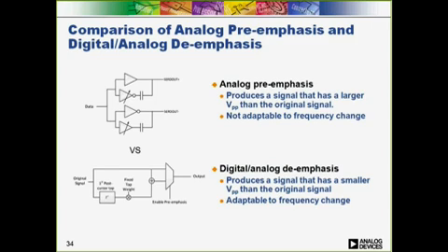This slide summarizes the differences between the emphasis methods that ADI uses on our JESD204B transmitters. The AD9250 uses charge injection to implement pre-emphasis. Using this method will result in a larger voltage swing at the output. Our second and third generation JESD204B transmitters use de-emphasis, which normalizes the voltage swing to the high frequency content, so it is lower.